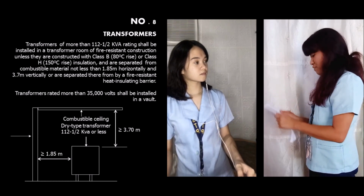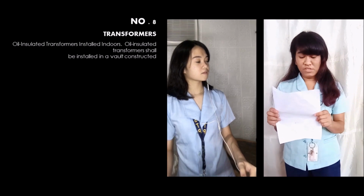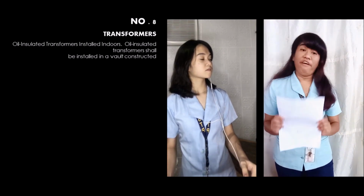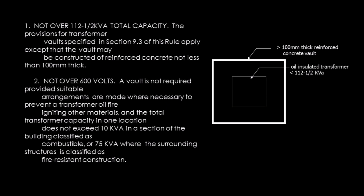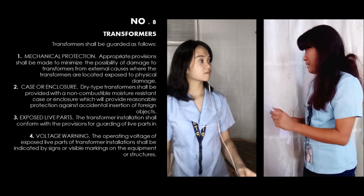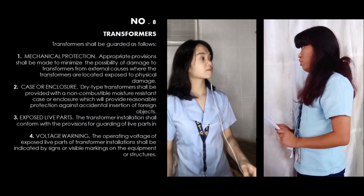Transformers rated more than 35,000 volts shall be installed in a vault. Oil-insulated transformers shall be installed in a vault constructed and specified in this section. However, there are exceptions shown on the screen. Transformers shall be guarded as follows: mechanical protection, case or enclosure, exposed live parts, and voltage warning.